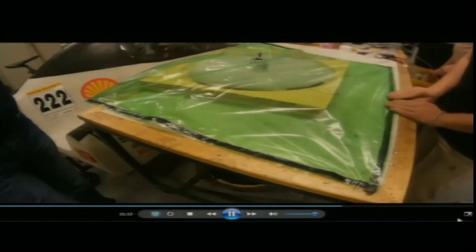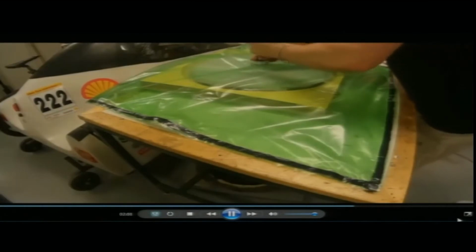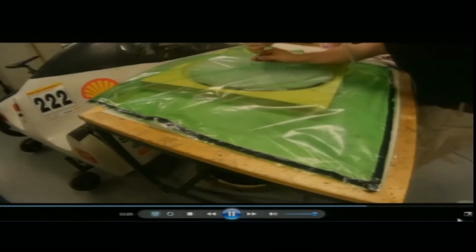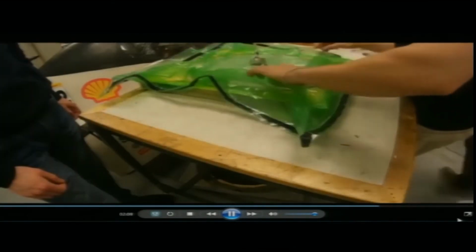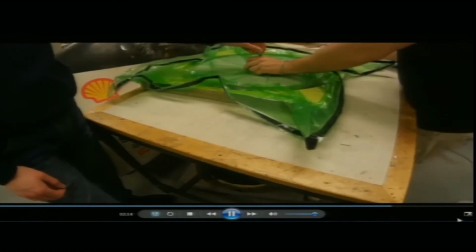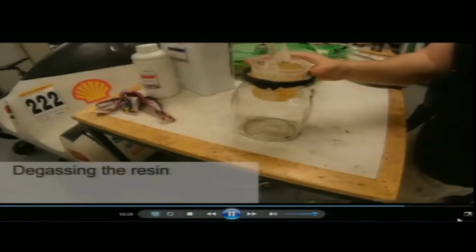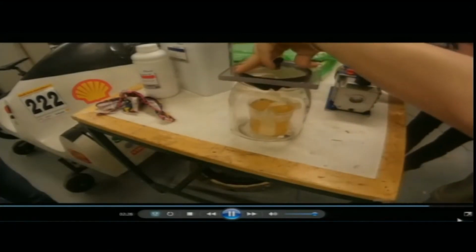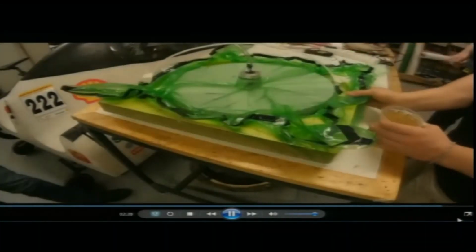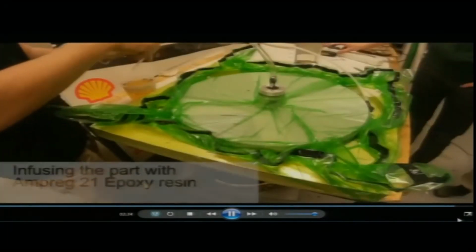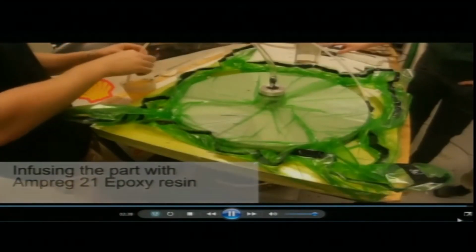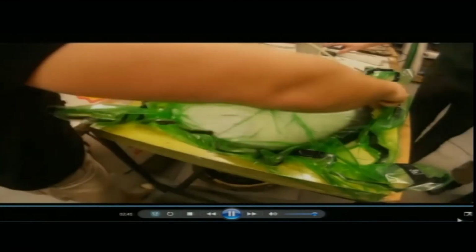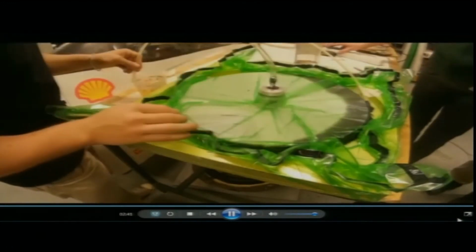Now, they are applying a vacuum forming here, as you can see. I told you that pressure is needed. Now, you can have positive or negative pressure. In this case, they are applying vacuum here. The role of the pressure is that the resin will get very nicely and uniformly wetted everywhere, so that it is not that there is a resin pocket somewhere, more resin somewhere, less resin somewhere. And here they are using the epoxy resin, as you can see from the side.